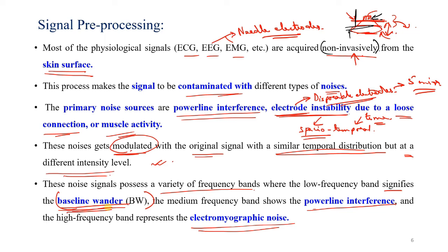Suppose you have started acquiring the signal in the morning session. At that time we have a very comfortable temperature, say 25 degrees centigrade. Now you are taking the signal continuously, and in the afternoon the temperature in the room increases to say 35 degrees centigrade. Since there is a change in the temperature, the resistivity of your electrodes and the acquisition system must have changed.